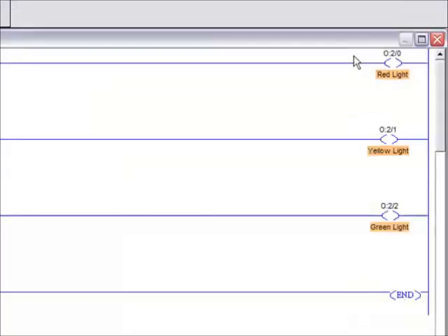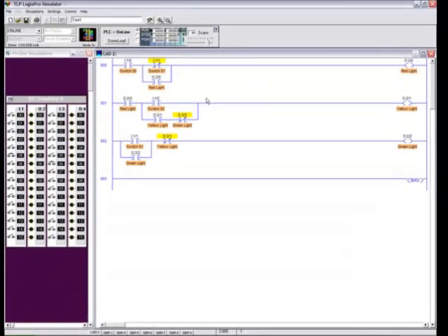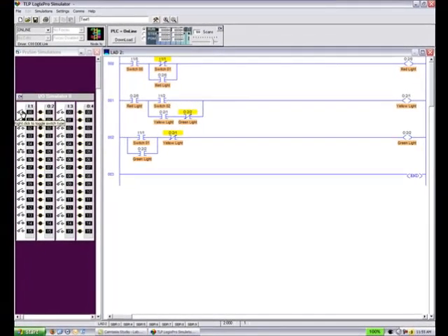With our program in run mode, we're executing the logic here. We'll go ahead and close switch 0, and we energize or turn on our red light. And if we look at rung 1, we need to, based on our skills, follow the ladder logic here. O:2/0 is now true, or it's on because we're highlighted yellow.